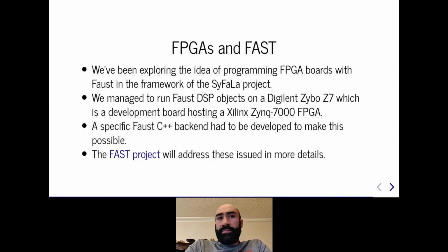While our system already works, it is currently hard to control audio processing parameters in real time. Moreover, generated IPs are relatively inefficient, probably due to the use of floating points. Next steps consist in generating fixed-point DSP objects to further optimize produced IPs and improving the control of processing parameters.